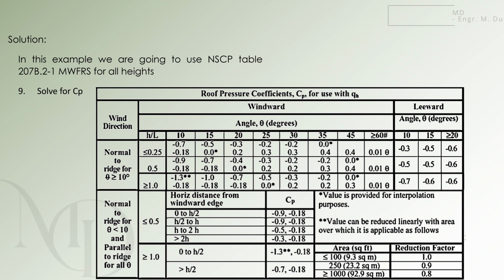For the external pressure coefficient on roofs, the code presents a more detailed table. Unlike the walls, the roof coefficients vary depending on roof slope, the specific roof zone, and the direction of the wind. Some roof areas may experience suction, while others may carry positive pressure. This makes roof analysis more involved compared to the simpler case of walls.